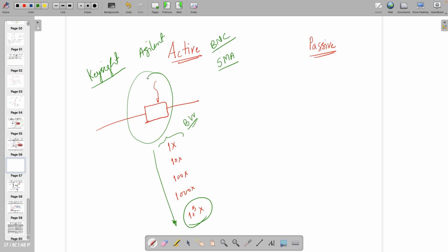So how to achieve higher impedance? What is your answer? How to achieve higher and higher impedance? So one option is to use cascode inside it. Second option, gain boosting, right? Add big circuitry, and at the tip there are actually JFETs used in this particular probe design, so that it gets a little bit heated up and then it's used. But active probes are a big market.